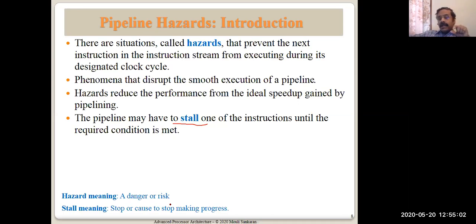The memory access creates a page fault. Now the instruction will be re-executed. I mentioned it in the OS course. The instruction which created a fault will be started again. That means that instruction, whether load or store, or even a PC access, will be started again. The pipeline will be filled again, so it will come through the pipeline again to execute that instruction.